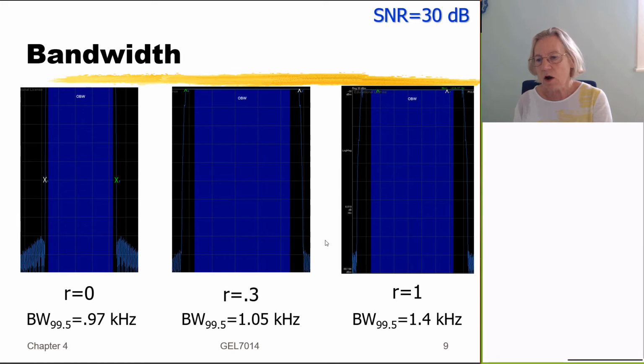Now we can see here also that there is something I would call the absolute bandwidth. You can see there's sort of a noise floor that's visible here. When the signal gets down into the noise, somewhere around this level, I might call that the absolute bandwidth, because I can see where the signal disappears. But there's not much energy in that last fall off. This is, of course, on a logarithmic scale. And so when it looks for the 99.5%, it's showing me a bandwidth, highlighted in blue here, which is somewhat narrower than what I would call the absolute bandwidth.